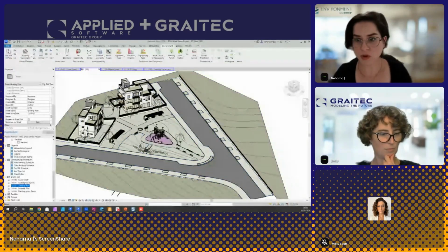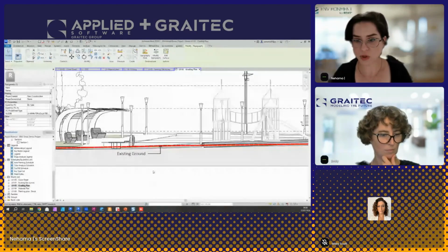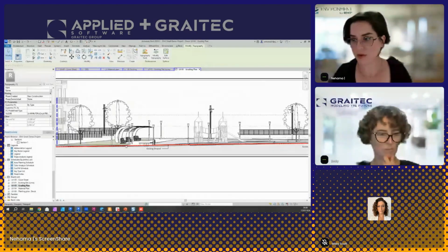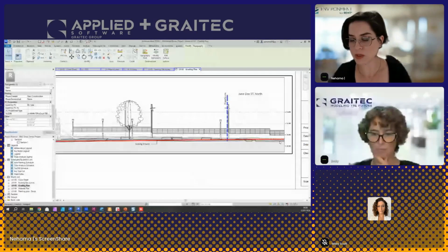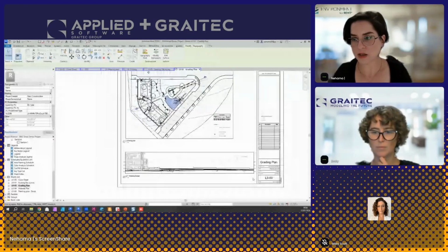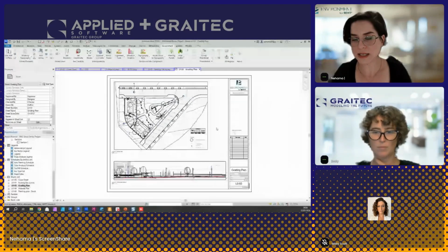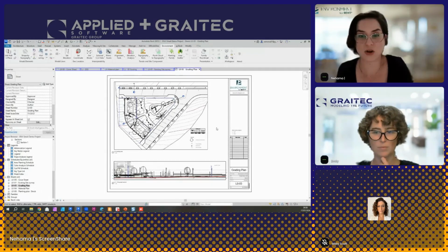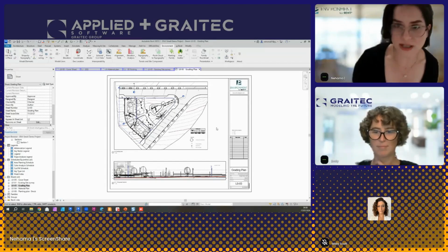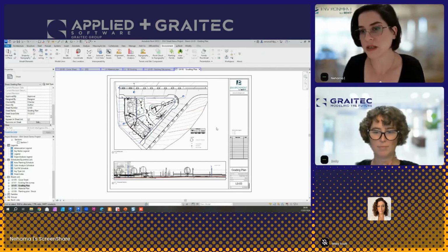And you're able, in this example, to show your existing ground in every section separately from your proposed design. So that for me is already a form of analysis that was not available to me working in CAD. And this is available so quickly. I remember my first Revit project where the client asked me, do you have an estimate of the cut and fill quantities? And I was so happy to get this question because I could email the answer to him in like 5 minutes. So that alone is a very strong, very powerful analysis tool in Revit, I think.